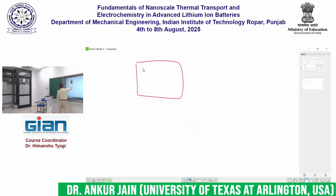So suppose I have a two-dimensional plate and I have a bunch of nodes inside this plate where this node is the i comma jth node. So my counting has to use two variables now, i and j. So this is T of i comma j, and if there are n nodes in each direction in x and y, then I have n square unknowns. But the principle remains the same. My governing equation is d2T by dx2 plus d2T by dy2 equals 0,